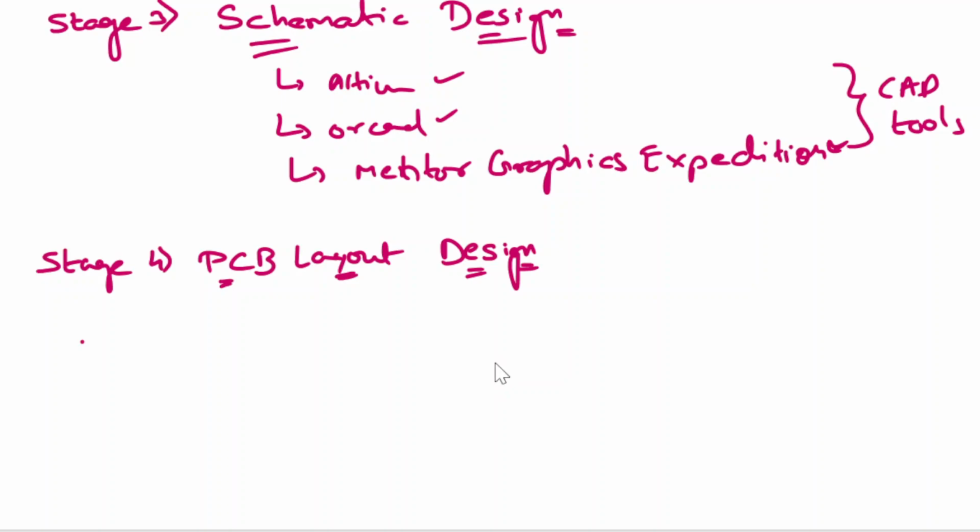You talk to your PCB fabricator or your PCB manufacturer first and check if they are able to meet your design requirements. So what are those design requirements? Such as the PCB stack-up layout, whether the number of layers can be made or not, what the minimum trace width requirement is, or the characteristic impedance for high-speed signal traces and differential signaling. All these things, whether he is able to manufacture or produce them, you need to check with your PCB manufacturer or fabricator.